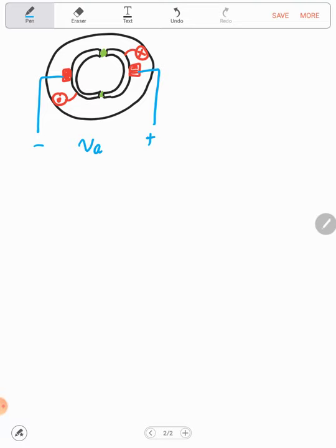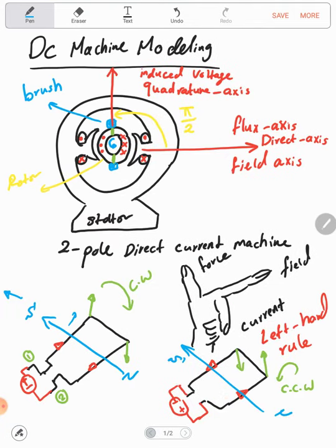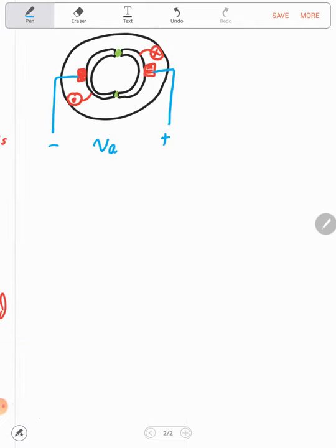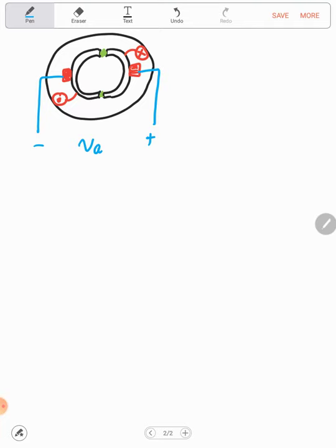So in this case, while the rotor is rotating, the direction of the current will be maintained under the field pole. So in this case, we can achieve a unidirectional torque and a rotation. Now, in general, for the machine, we are calling stator and rotor. In the DC machine, the rotor is called the armature. Why? Because the induced voltage is induced in the rotor.